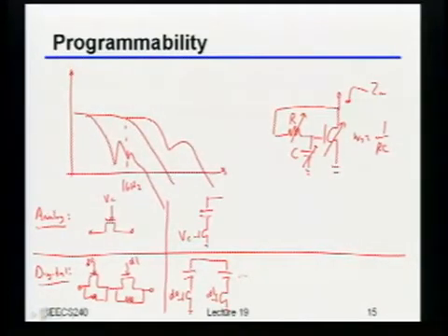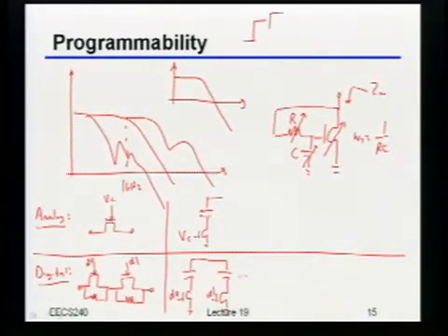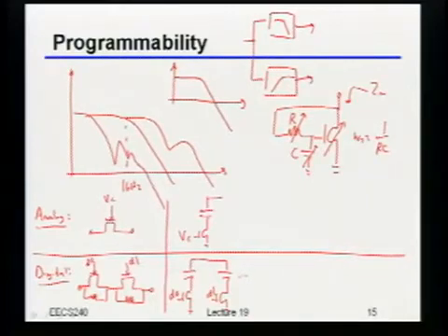But just as an example, let's say you always had a first-order low-pass channel. Then one of the very simple things people do is take the input signal, feed it through a low-pass filter, and also feed it through a high-pass filter. Then they look at the magnitudes of those two signals.